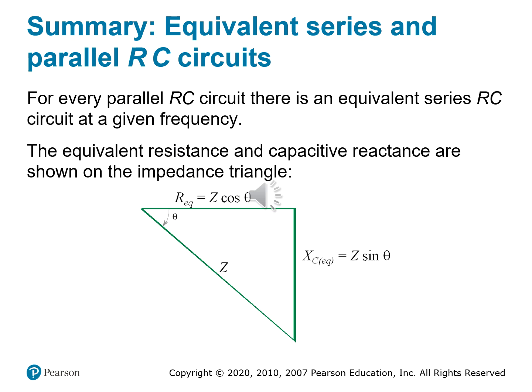So let's get back to the impedance triangle. On this slide, you see that the geometric shortcut helps you convert the following. The hypotenuse of the triangle is the total impedance. Always remember the horizontal side is the equivalent resistance. So R equivalent is equal to the impedance Z times cosine theta. And the vertical side is the equivalent capacitive reactance. So X sub C equivalent is equal to Z times sine theta. The triangle is not just geometry. It's not just something to look at. It's a translator between parallel and series circuits. And this is like the basis of how it works.